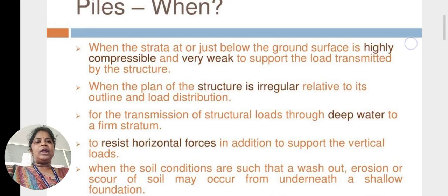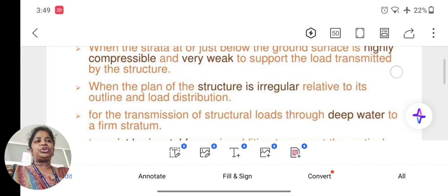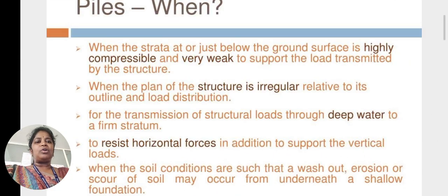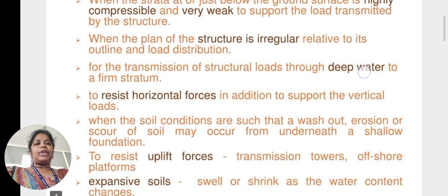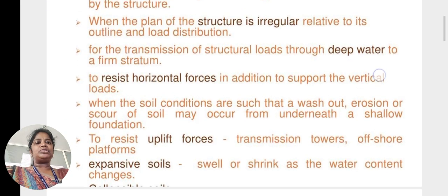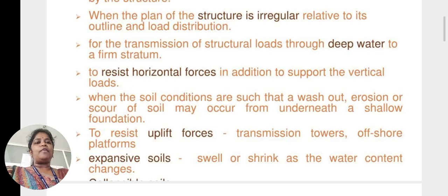And when the soil conditions are such that a washout or erosion or scour of soil may occur from underneath a shallow foundation, then we need to use pile foundations. And also to resist uplift forces in transmission towers, offshore platforms. Mainly the uplift forces occur in transmission towers, offshore platforms, and some other taller structures.